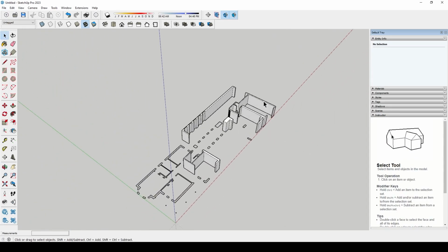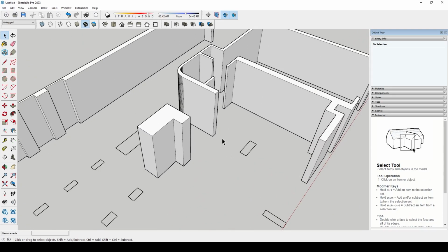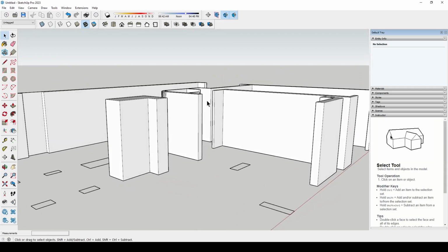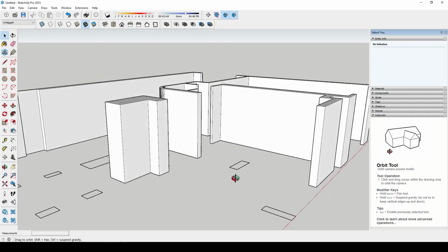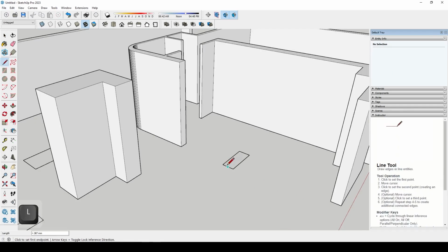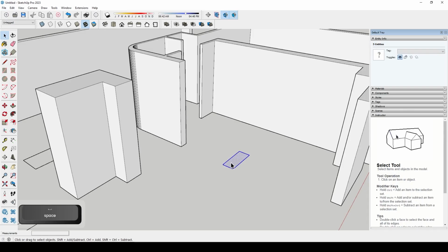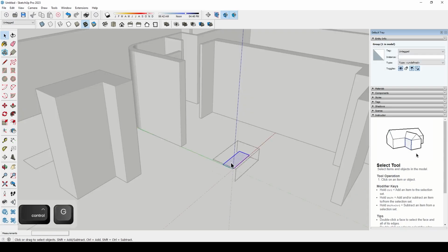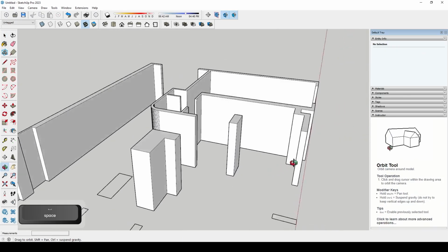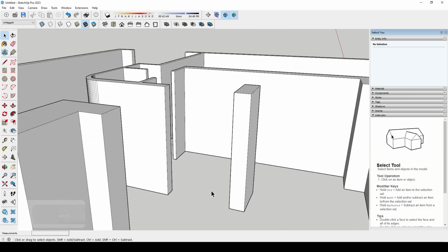All right, let's go ahead and add in some cabinetry that we've got here, which sits inside this space for the kitchen. So first thing we're going to do is build the other side of the island. So L for over here, double click, Control G, double click, beautiful. All right, we're going to have an island which sits at 900 above floor level inside this space here.